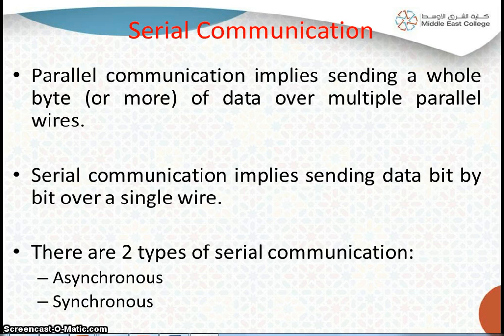In the previous classes, you might be knowing that PIC16F microcontroller has 5 input-output ports where we can send multiple bits of data over multiple wires at one time. That is what we call parallel communication. On the other hand, serial communication implies sending one bit of data. For that purpose, a single wire would be sufficient.